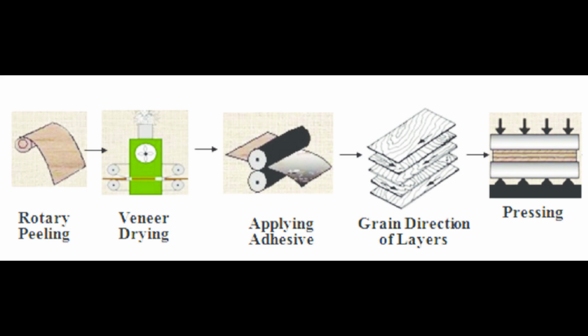The sheets are then patched, graded, glued together, and then baked in a press at a temperature of at least 140 degrees Celsius and at a pressure of up to 1.9 megapascal, that is around 280 psi, but more commonly 200 psi, to form the plywood panel. The panel can then be patched, have minor surface defects such as splits or small knot holes filled, resized, sanded, or otherwise refinished depending on the market for which it is intended.